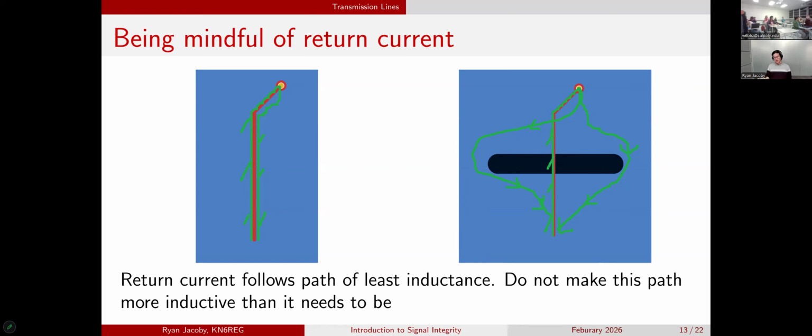So this is, I guess, an important part about transmission lines: they help you manage this return current path, and if you accidentally break that, the results can be very, very disastrous. There are resources online about signal integrity, and one of the things he says is that if you don't engineer the return path for your current for every single signal, it will find a return path, and if you didn't pick it out for it, it will be one that you do not like, and it will cause a lot of problems.